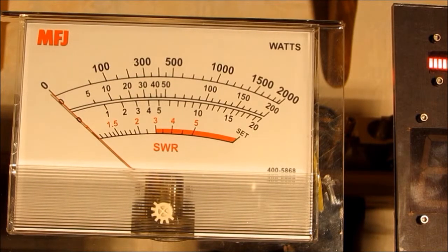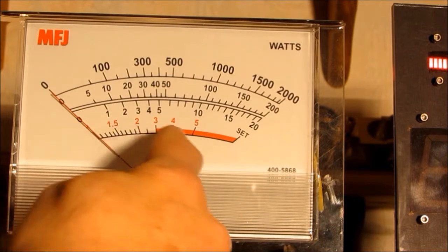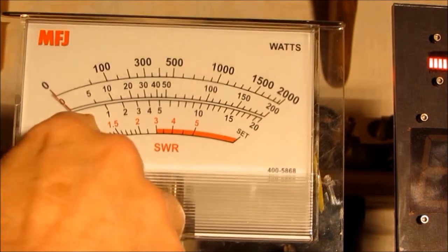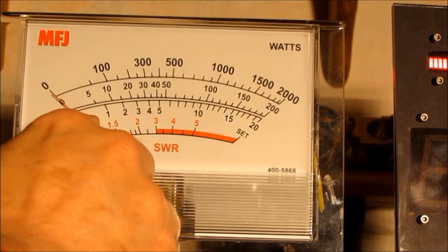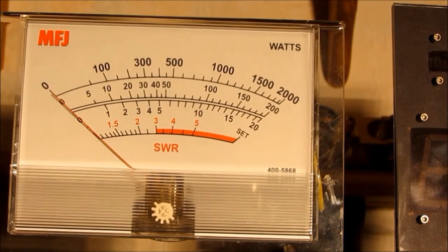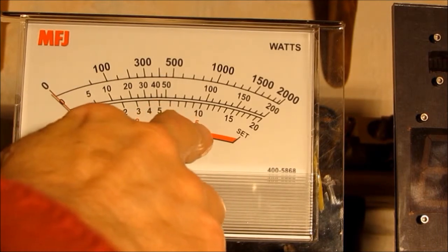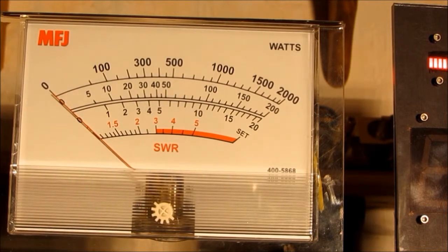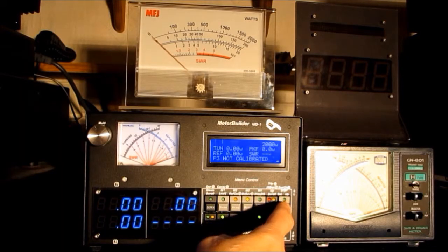But had I picked a number like 41, that would be workable, but it's going to give me numbers with strange decimal point values. Likewise, for the SWR, I can get pretty good granularity if I calibrate at each tenth, 1.1, 1.2, etc. Again, you just have to remember to subtract 1 from 5 because you're starting out in this particular case at 1. Let's go ahead and calibrate panel meter 3.